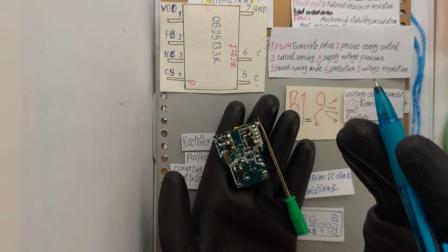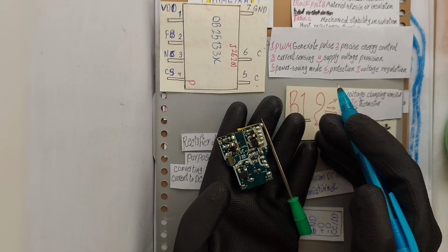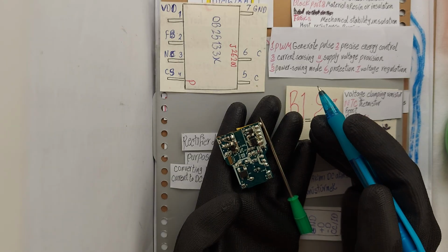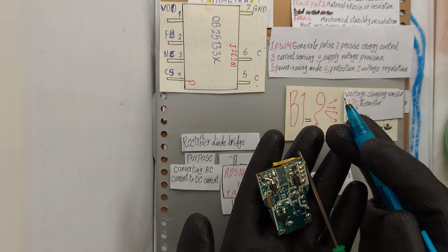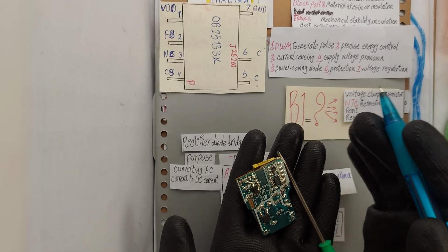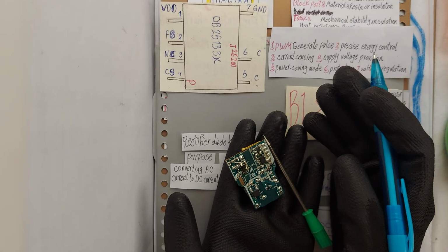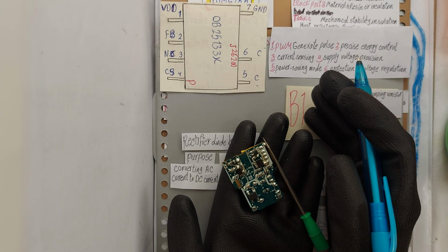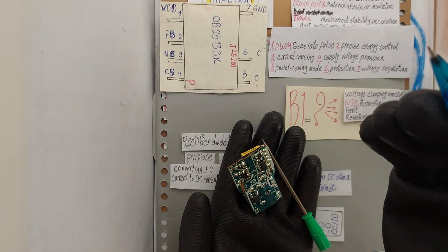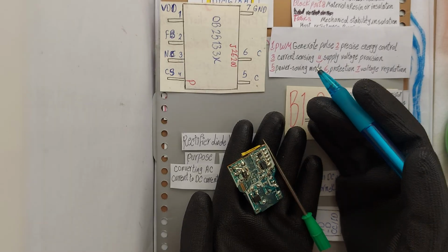The OB25133 IC is an AC-DC switching controller with primary side regulation (PSR) technology. It doesn't convert voltage on its own, but precisely controls the switching process in switching power supply circuits, such as mobile phone chargers. Main task in the circuit: at the first, generates PWM, pulse width modulation, pulses to turn the power transistor on and off. Precisely controls energy input to the transformer for voltage conversion.